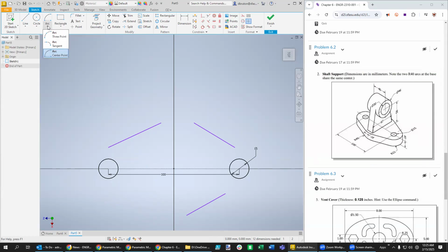So let's go ahead and place our arc down in here, center point arc, like this. And we can start it out here and go like that, and then make sure that we dimension it to be 22. Amazing how close I got on that one. And looks like I forgot to close this last line. And again, we do this on the other side. If you feel more comfortable going faster with perhaps making mirrors, then you can certainly do that.